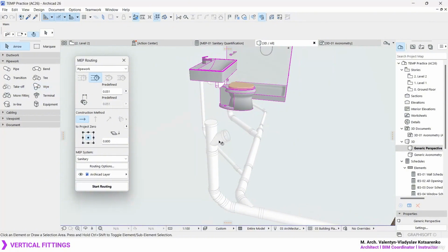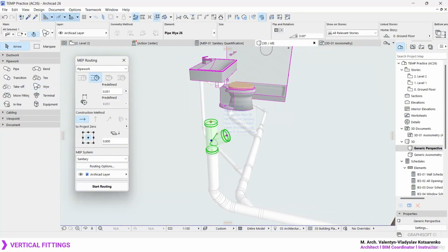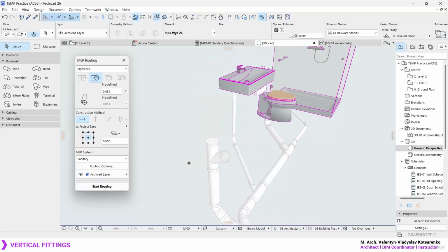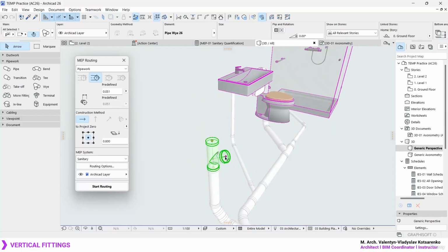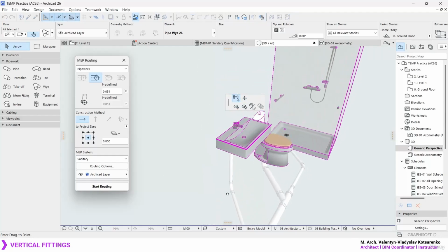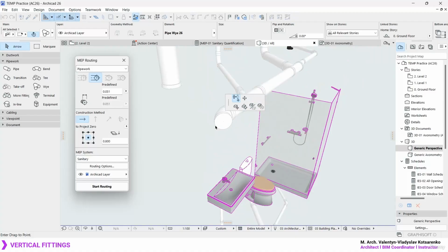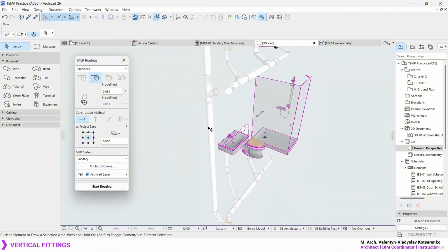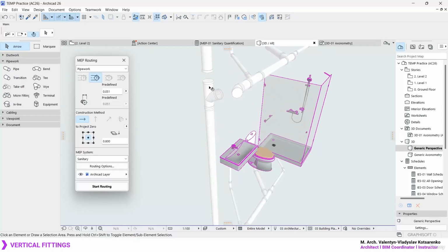So yeah, the most important thing is that you get a fitting that is correctly positioned. Doesn't matter the vertical displacement where, because you can also, for example, select your fitting and simply move this in line until it matches the position you are looking for. So let's see if we can position it in, for starters, over here. Right over here you can notice how the pipe has been adjusted automatically.